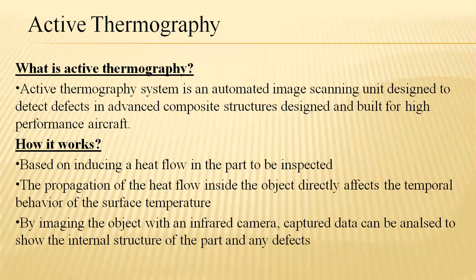So, coming to the working of it, how it is used. Based on the induction of heat flow in the parts to be inspected, the heat that is propagated inside the object directly affects the temporal behavior of the surface temperature.